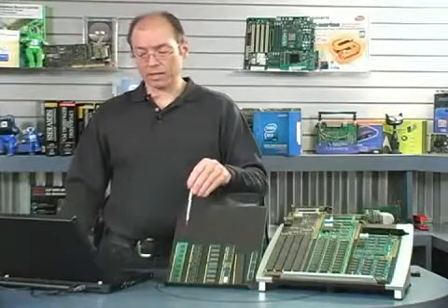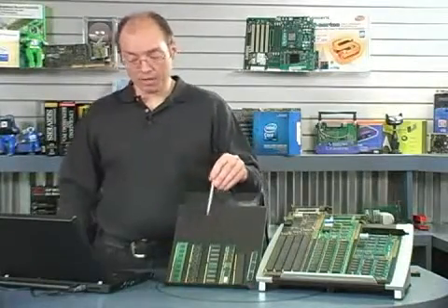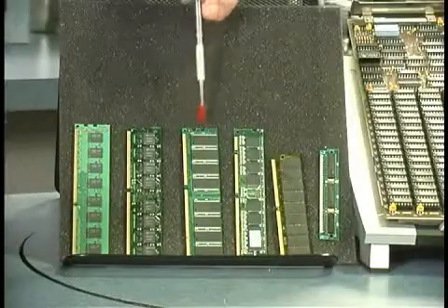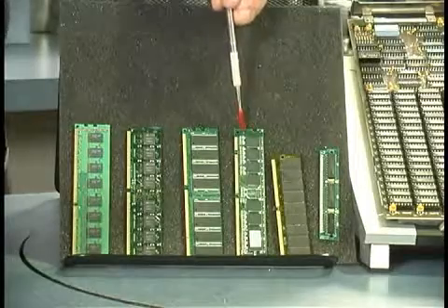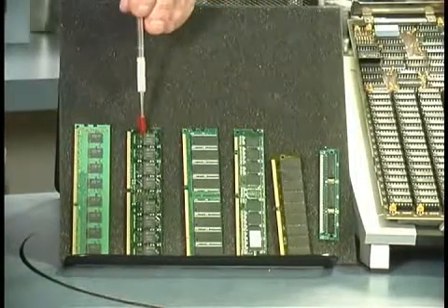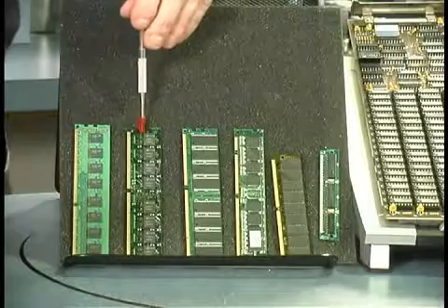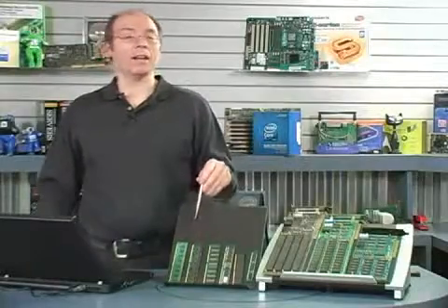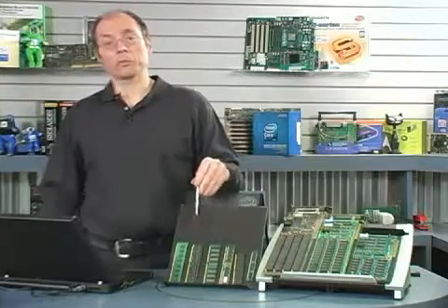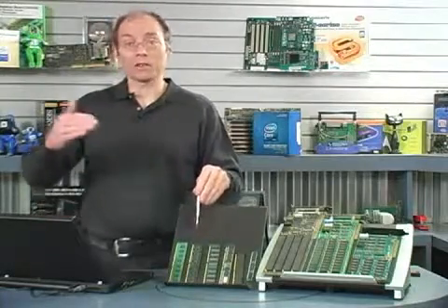Now let's take a look at how this technology works. We mentioned that double data rate ran at twice the data rate of the single data rate modules. Now DDR2 is not like a quadruple data rate. What they did there was add extra signal pins in order to improve signal integrity, so the clock could go higher.